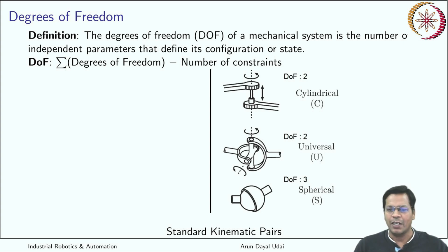So that is maybe a cylindrical joint. That is a cylindrical joint. A universal joint, so you see how many definitions you require for this. It is 2 only. If you are not allowing it to move vertically upward, you can constrain it. You should also constrain the rotation degree of freedom. So constraining that will fully constrain it. So 2 definitions are required.